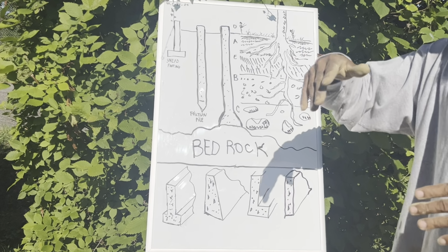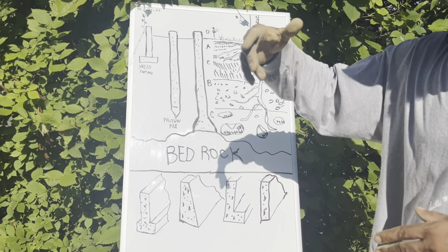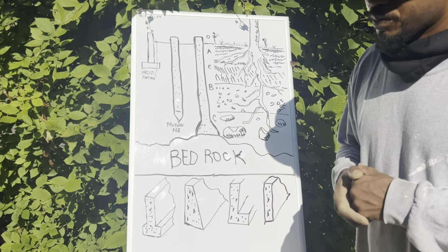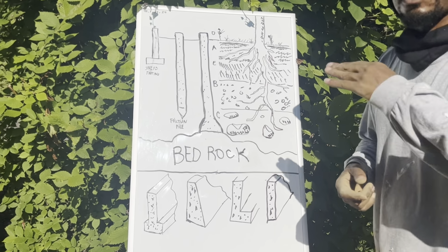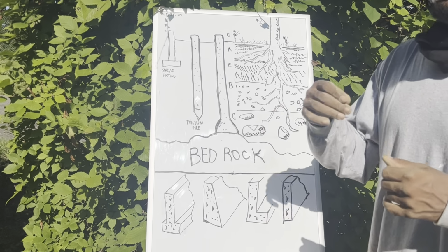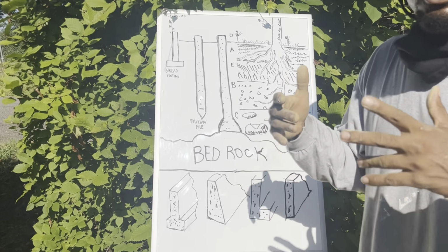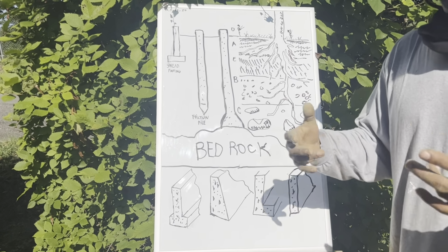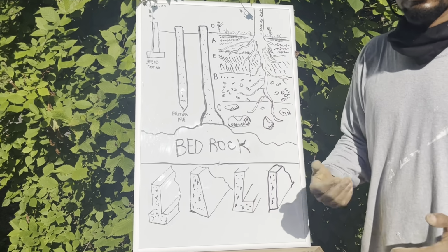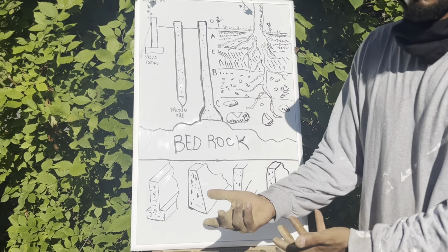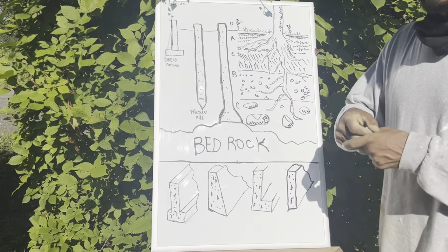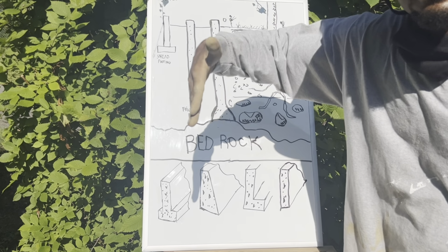And you can move on up as you get to silt and sand, it'll begin to be heavier, because when you're dealing with these different types of soil, you're dealing with different soil sizes, okay? So clay is real fine, a real fine type soil, smaller, okay? Then silt is a bigger grain, a bigger particle. Then you move up to sand, that's even larger. And as you move on up to gravel, that's even bigger. And so depending on the size of your grain or your soil particles, that's going to determine how the soil drains, okay?